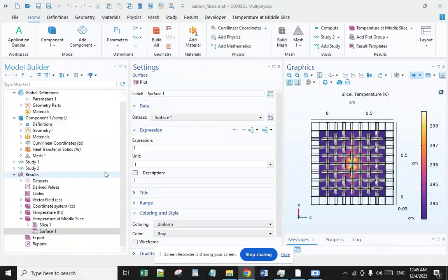They found that the through-thickness thermal conductivity of non-crimp carbon fabrics and twill woven carbon fabrics increased with increasing fiber fraction until the packing fraction was reached at about Vf equal to 0.43 and 0.50 respectively, which might be attributed to the corresponding increase in contact points and contact area up to the packing fraction.